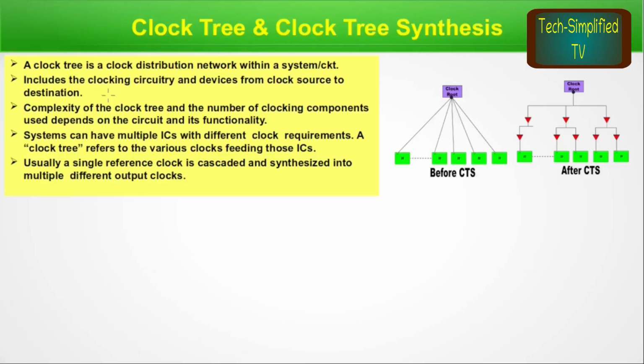A clock tree is a very important and integrated part of a circuit or chip. A sequential circuit works as sequential because of the clock. In a circuit or a design, the clock signal must be present in each and every sequential leaf level component or flip-flop. Therefore, the clock signal has to travel a longer path, and we already have discussed that in the power management series. The clock signal travels a longer path and consumes a lot of power. So that is very important from the aspect of power management.